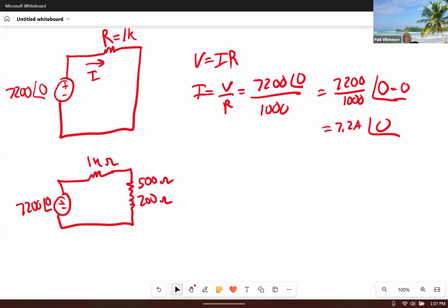So because this is a 200 ohm inductor and not a resistor, I can't just call it 200 ohms, can I? I have to add the J term there, don't I? Otherwise, when I do Ohm's law, I would add up 1000 plus 500 plus 200. That ain't going to fly, right? Because that's not a 1700 ohm equivalent resistance. It's a 1500 ohm equivalent resistance plus J 200 ohm equivalent impedance. So my Ohm's law is still applicable, but I'm going to tweak it a little bit.